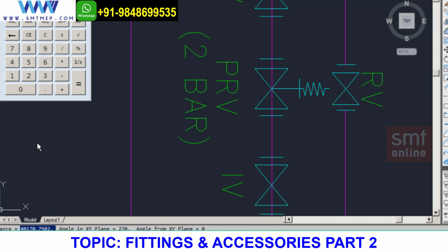So I need to divide, multiply or what? First of all, very good. So times 3.28. I got this in terms of feet. Now put this in the formula. P equals 131.76 or something like that, times 0.433, I'll be getting in terms of PSI.